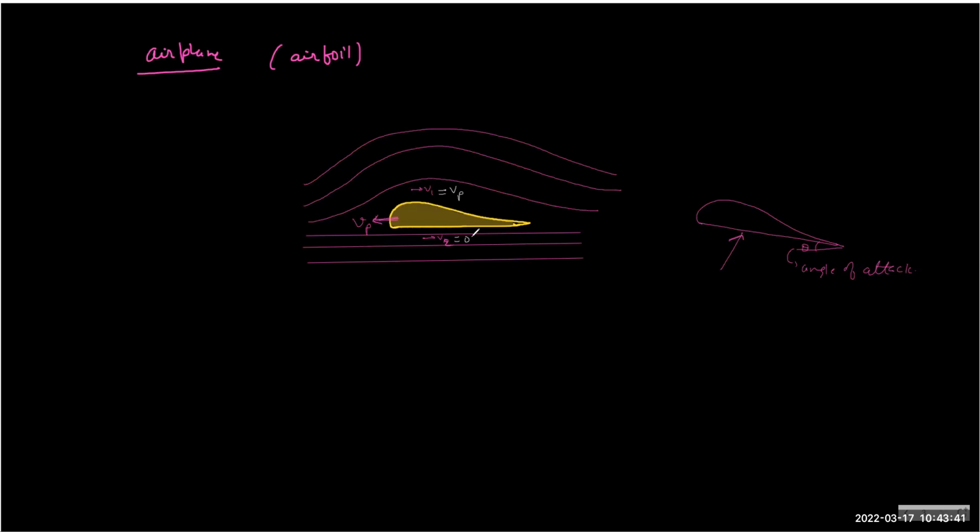So either you can think of plane moving through the air, or you can keep the plane fixed and air is moving across the plane. That's the same thing in a relative frame. Because the Vp is there above and below is nothing, the pressure below is going to be very high compared to the pressure above. And this gap, the vertical height, is almost negligible, so we can ignore the third term, again if you remember, by considering this as a reference, and the size of the wing is not much, so we can write that P1 plus half rho V2 square,